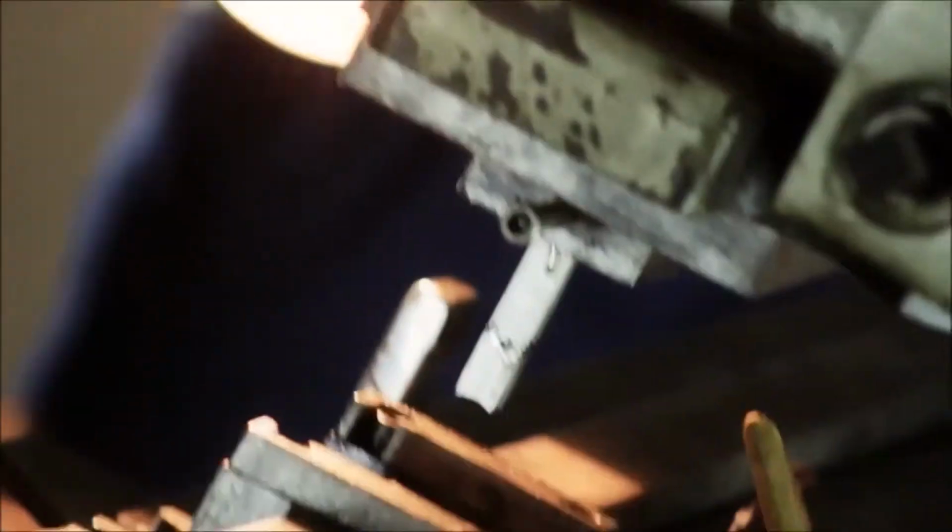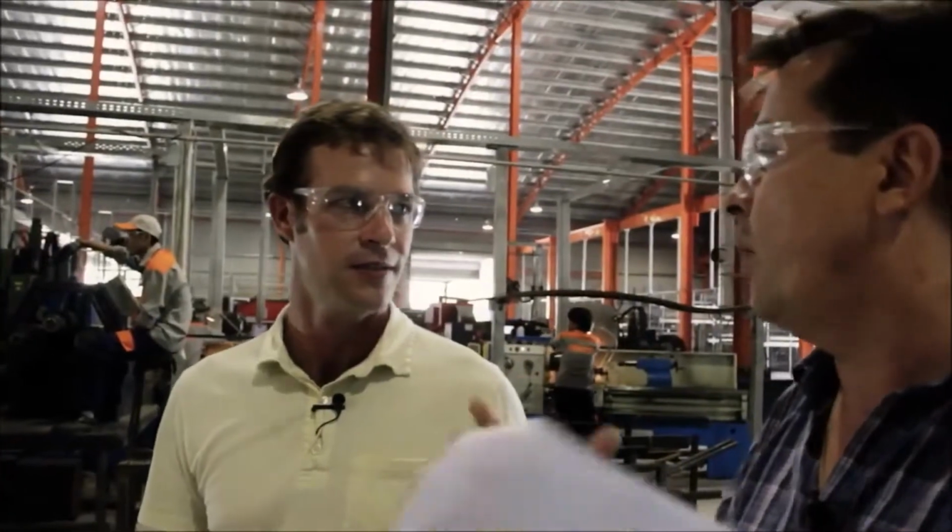Because the product is hot dip galvanized, the product must be fully vented. So we have to drill the tubes with holes or punches for the venting process of the hot dip galvanizing. So you're drilling all of the holes, so when the fabricated gates are dipped in the molten zinc, all of that air expands and is allowed to travel outside the gate. If we didn't do that, the gate would explode. Well, and that also allows the inside and the outside of the tubes to be fully hot dip galvanized.